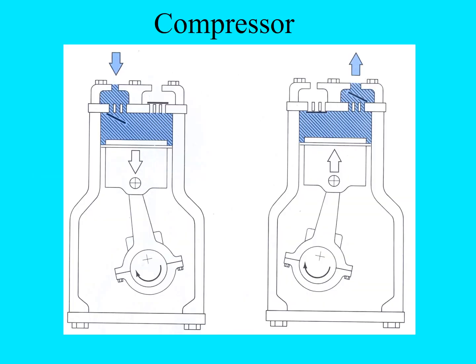So this is showing a cutaway of a compressor, and this is the early style. But as the piston pulls down, refrigerant vapor is going to be pulled into the cylinder. And you can see there's a little reed valve that just pops down.